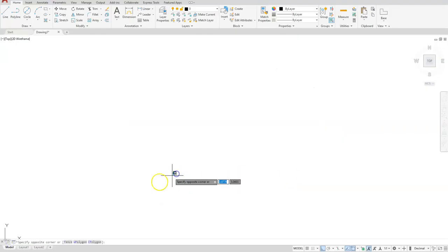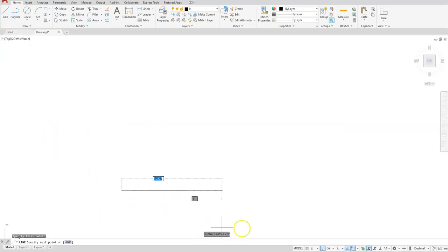Okay, so in AutoCAD, we're going to start with the line command. And I'll start with that lower left corner like I showed you. Let's go ahead and make sure that we have ortho turned on, so this little icon should be blue. Let's go ahead and give it our preview direction so you can see that I am rubber banding this direction. And let's go with the apostrophe CAL command just for the calculator. And our expression will be 4 minus 2.25 minus 0.25 and minus another 0.25.